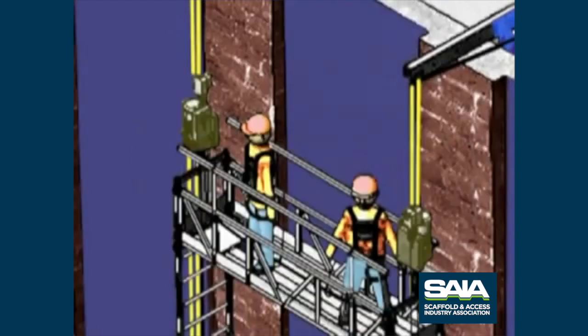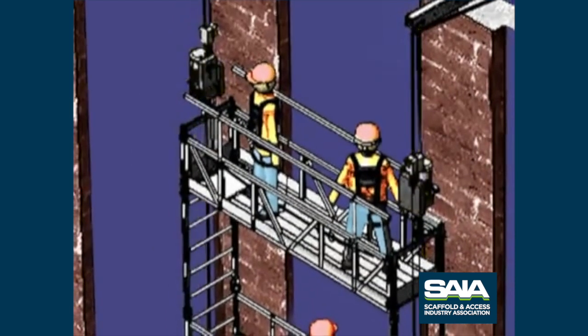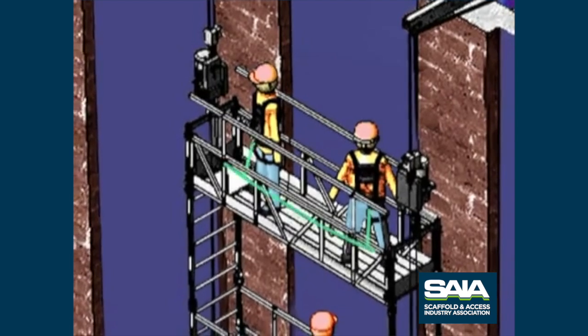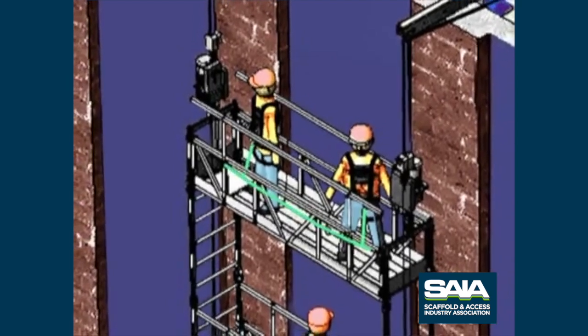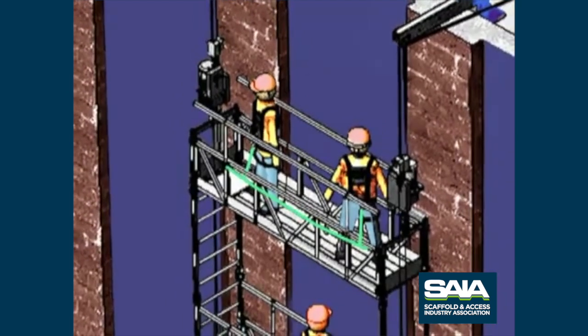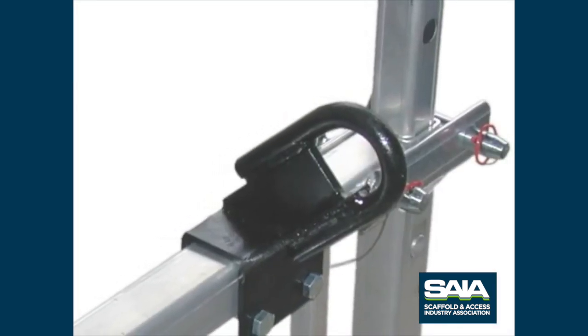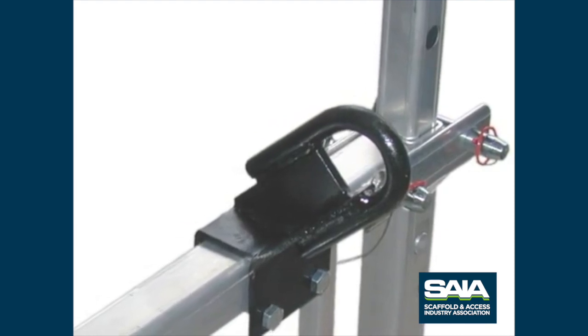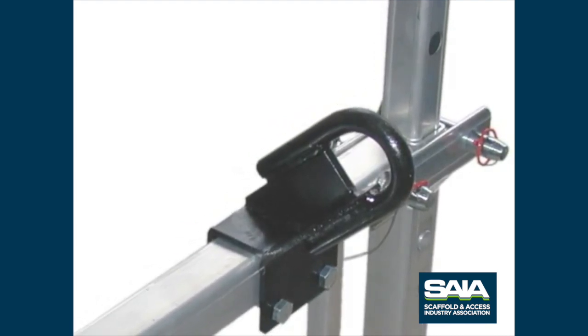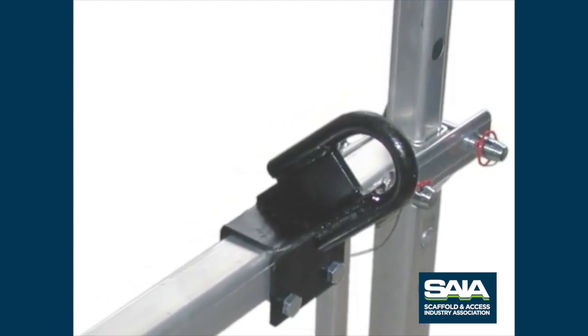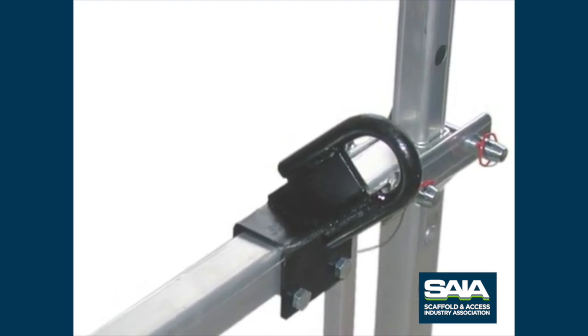Where workers are required to move back and forth along the stage, a horizontal lifeline should be installed along the back of the stage to which their lanyards may be attached. Both ends of the trolley line must be attached to a structural member of the stage. In order to minimize the distance a lanyard would travel on the trolley line, mechanical stops should be installed at distances not to exceed 10 feet.